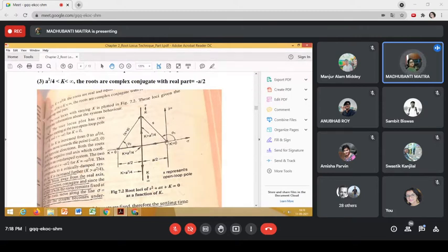So that means since both the roots are real, we can say that the first root will start describing a locus with k, right? And as k is increased within that particular range, this root will start moving along this negative real axis in the direction of this arrow. And the second root will start describing a locus again along the negative real axis, but in the opposite direction, in the direction of this arrow. Am I clear?